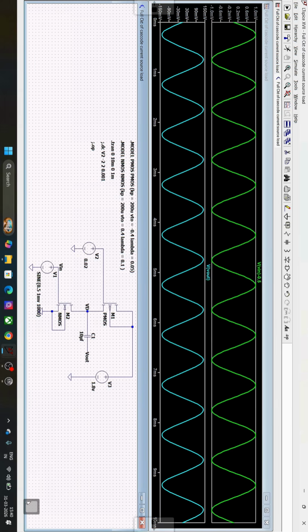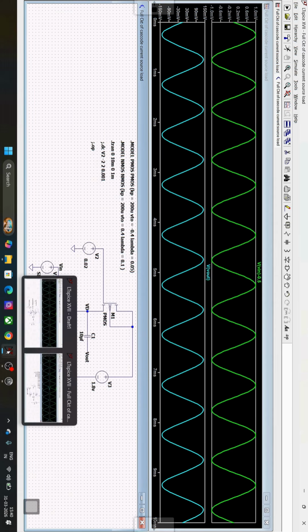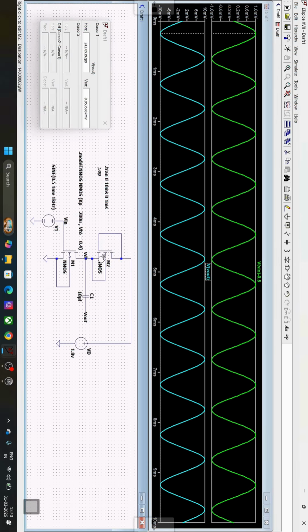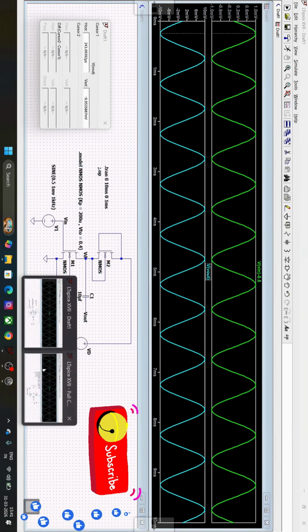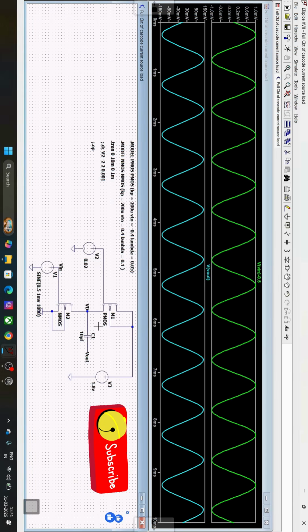But when we introduce the concept of a diode connected MOSFET, that means a CS amplifier with a diode connected MOS, we get rid of this biasing point. That's the advantage of a diode connected MOSFET. That's why we connect this diode connected MOSFET as the load of the CS amplifier, to avoid the biasing distortion which we were facing in this particular circuit.